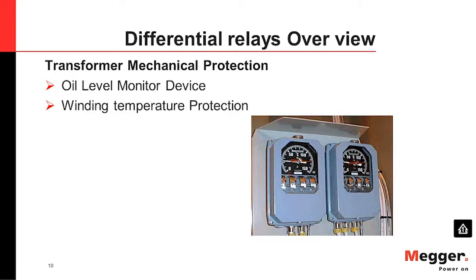The first stage will maybe start the fans. The second stage will start another set of fans or motors, or let's say the pumps. And then in some cases, we'll have an alarm, like the third stage, an alarm to the control center that you have an overheating problem. And the fourth stage will be the tripping. So we can still have a trip, and we don't need to have a trip if it is a monitored station.